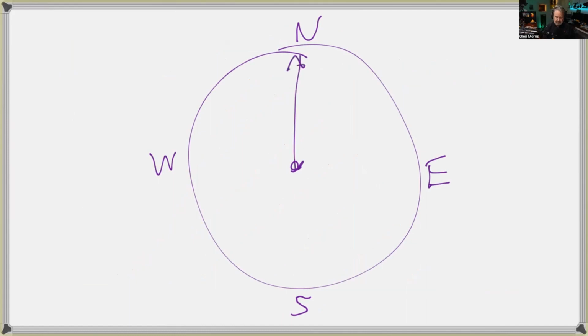So facing north, and I should point out, the convention is equator facing. So in the southern hemisphere, facing the equator, which is to the north of us, this is 0 degrees. And therefore going around clockwise, 90 degrees, 180 degrees, 270 degrees. So you'll talk about an orientation of, say, a roof based on the azimuth. So if I say it's a 45 degree azimuth roof, what direction is that?